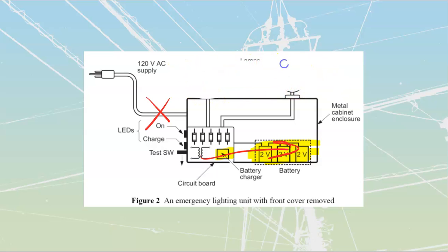And when we do that, what we'll do is wire from here. We'll take DC wiring out to remote mounted lights that are going to be in other locations inside of our building. It's another common way for these things to be done. We do want to make sure that this stuff is going to be mounted up high, to keep it out of the way of accidents, vandalism, anything like that. It's designed to be a fail-safe emergency type of system.